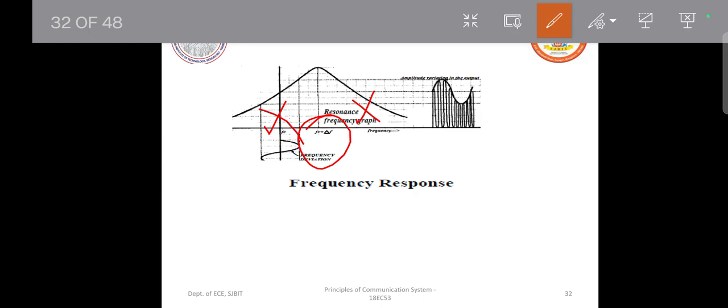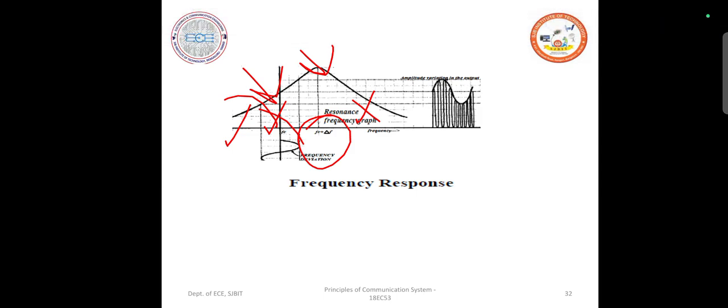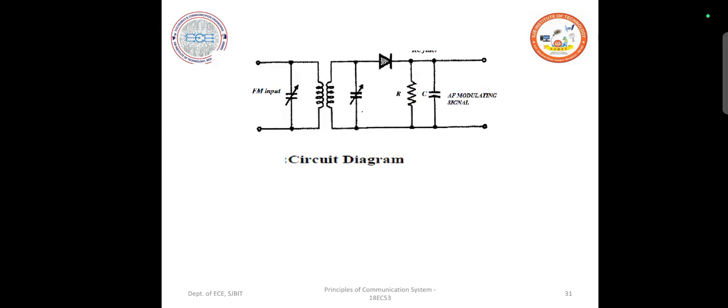So this is kind of the reverse process of what we did in the frequency modulation block. So when the frequency comes back to FC minus delta F, the amplitude reduces because it is at this particular point, FC minus delta F. So this is FC plus delta F. This will be the FC point. That will be FC minus delta F. So what you see is a linear curve which shows an increase in the voltage as well as a reduction in the voltage. So this is what we are expecting. This is how this circuit is going to behave.